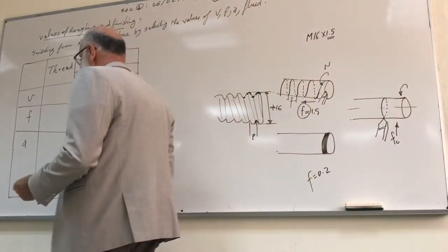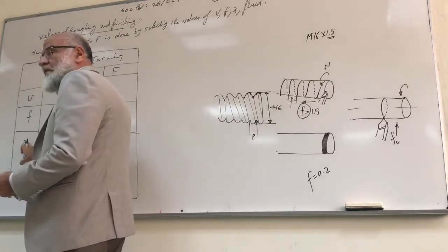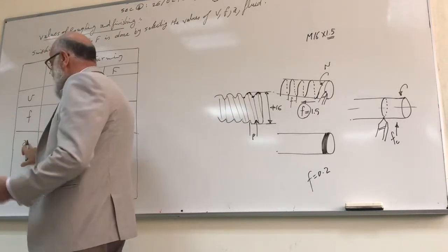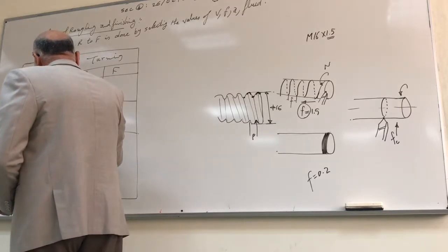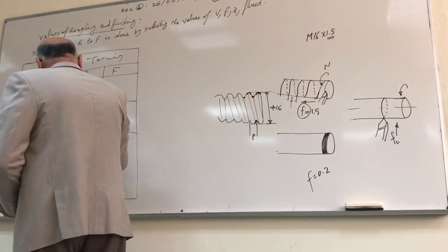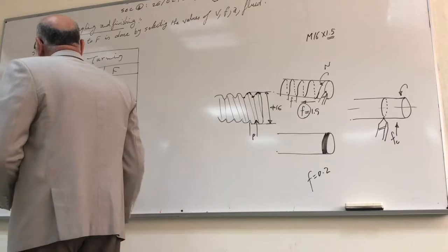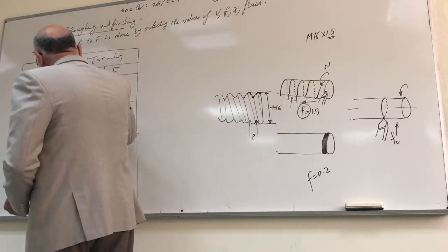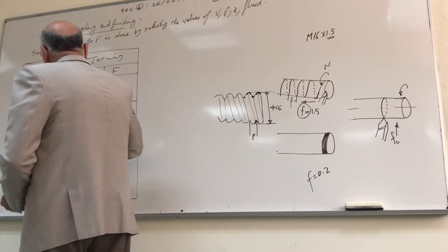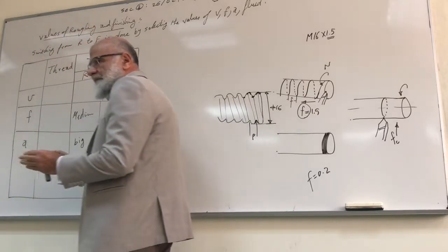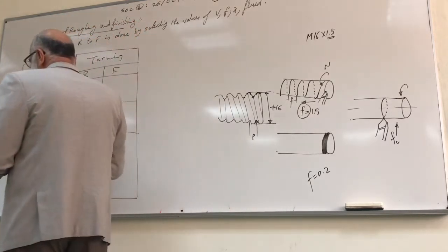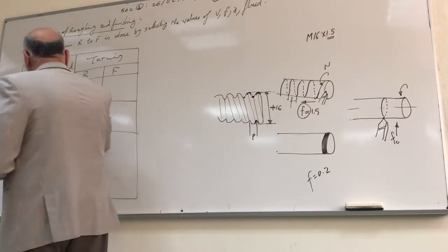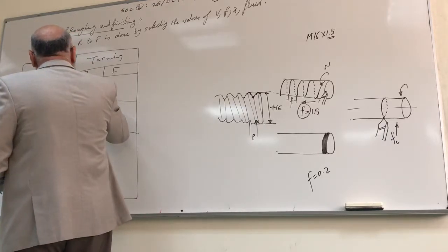Therefore we should remove a large area, A equals depth of cut times feed. But we should increase the depth of cut, a big value, and the feed a medium value. And due to the power constraints, power is constant, therefore I will take a slow speed.